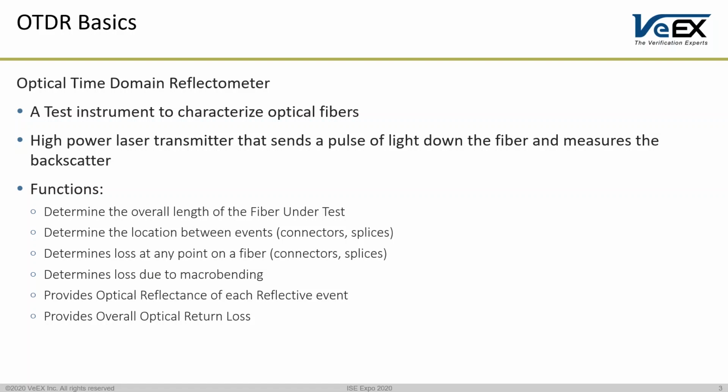There are a number of reasons why you would use an OTDR. Determine the overall distance of the fiber, determine the location of the faults, the defects, or any events along the fiber as well. Determine what kind of events can happen at what distance. An OTDR can also calculate the loss of each of these events. We have a measure tab that will have markers, and depending on where you place the markers, it will give you measurements from an A marker and B marker side.